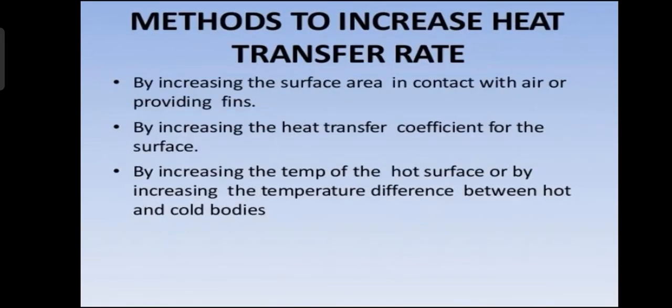Methods to increase heat transfer rate: by increasing the surface area in contact with the air or providing fins, by increasing the heat transfer coefficient for the surface, by increasing the temperature of the hot surface, or by increasing the temperature difference between hot and cold bodies. So if we want to increase the heat transfer rate, we can increase the surface area in contact with air or provide fins. So generally the fins are very useful to increase the heat transfer rate.